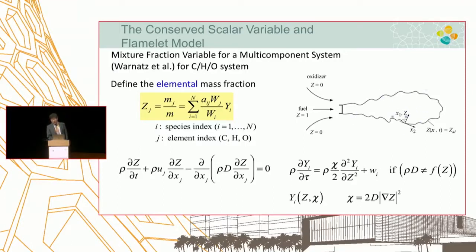As long as your turbulent combustion burns like that, you can simplify the chemical reaction by solving only the so-called Flamelet equation. And the transport in the 3D code only needs to deal with the non-reactive transport equation for mixture fraction. So this is one of the most commonly used, more advanced turbulent combustion submodels, which is more rigorous compared to other empirical submodels like multi-zone or PASR.